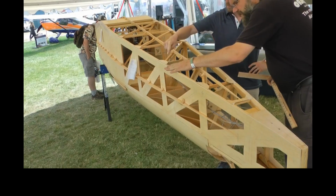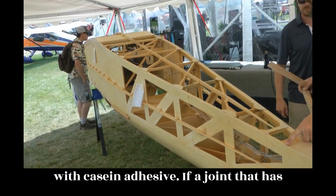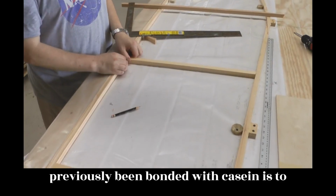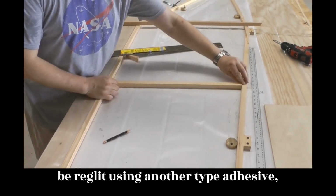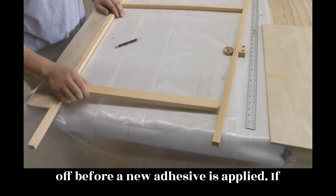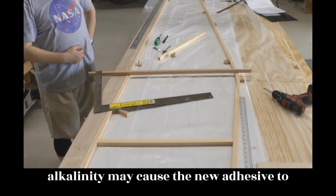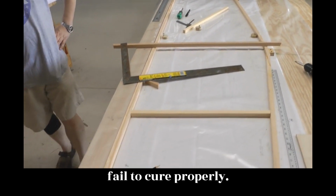Note: some modern adhesives are incompatible with casein adhesive. If a joint that has previously been bonded with casein is to be reglued using another type of adhesive, all traces of the casein must be scraped off before a new adhesive is applied. If any casein adhesive is left, residual alkalinity may cause the new adhesive to fail to cure properly.